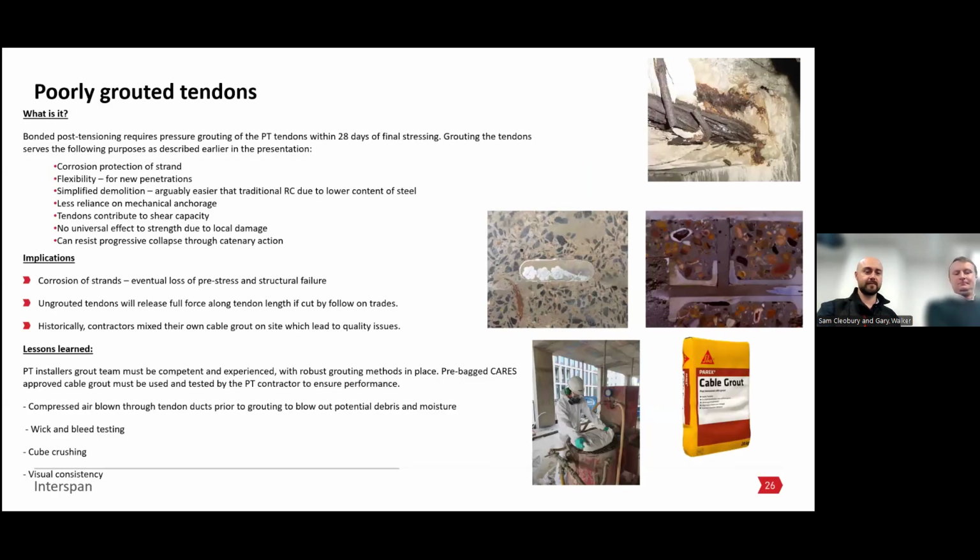Grouting, with a CARES approval, and we use pre-bagged proprietary grades and do the correct testing to be compliant with CARES and our own QA. It's essential that it's done properly. There are no voids within there because we don't want to see corrosion later on.